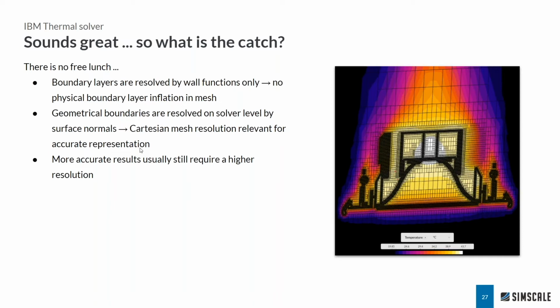And this gives you a very nice possibility to capture accurately boundary layer physics with the standard turbulence models. In this case, you cannot do that because you don't generally know how your surface will cut your background mesh. So you will have some kind of irregularities when it comes to boundary layer treatment, compared to, of course, the body fitted mesh.